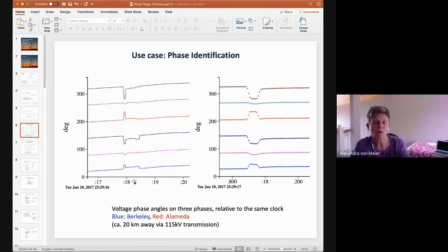And what we're showing here is you see that the phase angle doesn't hold constant, right? They all kind of drift a little bit upward, which tells us the grid frequency was a tiny bit greater than 60, not much, at that particular time in 2017. But we're not interested really in the absolute angle.